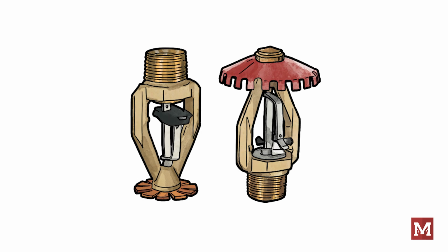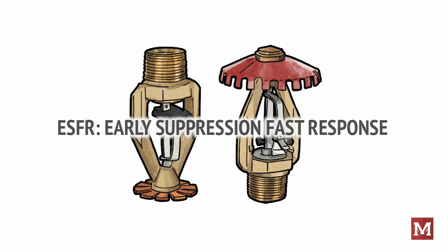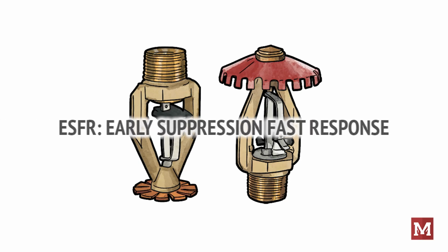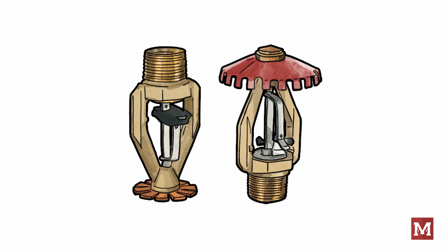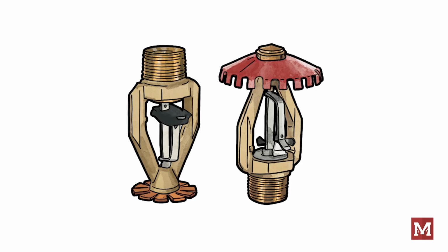Last, we have storage sprinklers that allow very tall storage without having sprinklers inside the racks. These are called ESFR. That's short for Early Suppression Fast Response. The philosophy of the ESFR sprinkler is to open at the very early stage of a fire, responding with a lot of water under high pressure distributed over a small area. ESFR sprinklers have their own unique way to do their hydraulic calculations, just like CMDA and CMSA.